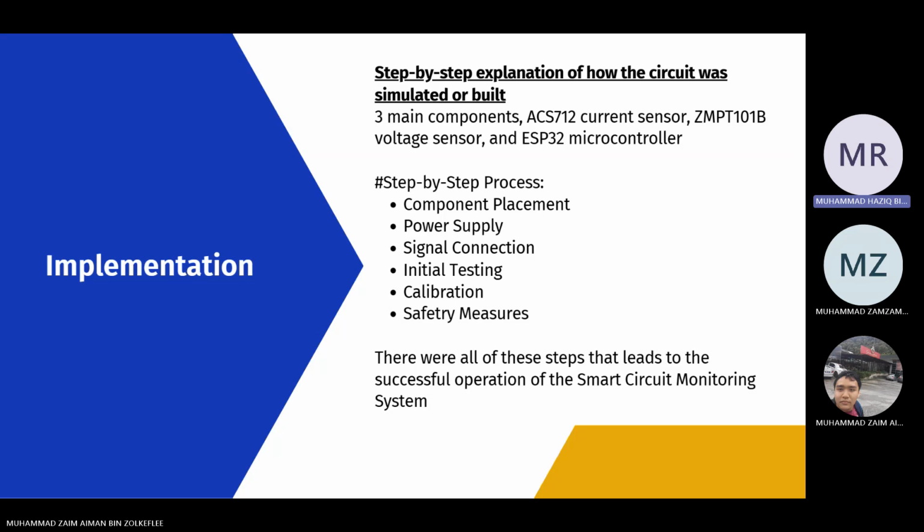Next is the power supply. Provide a stable power supply for the ESP32, usually 5 volt via USB or a regulated power source, and ensure that the sensors are powered correctly, typically 3.3 volt or 5 volt, depending on the specific sensor.